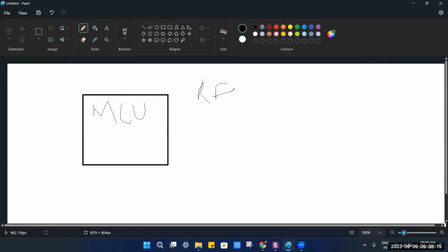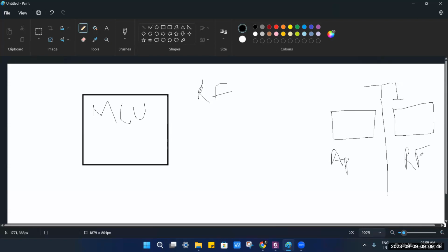So they have divided it in the latest ARM Cortex-M series. Like you were talking about NXP, TI has also done that. Maybe I will share it later. That one IC has a dual core microcontroller unit. One core takes care of the application part, and the other core takes care of the RF part. What does it mean?